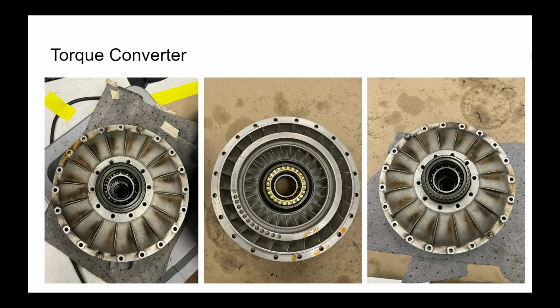to its transmission. This process is achieved through the utilization of the pressure gradient produced by rotating the fluid, causing the transmission oil to circulate between the impeller, which is connected to the engine, and the turbine, which is linked to the transmission. Additionally, torque converters are equipped with airfoils that generate torques as the oil moves radially within both the impeller and the turbine components.